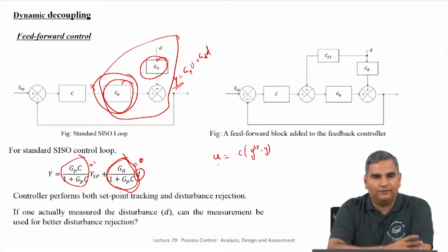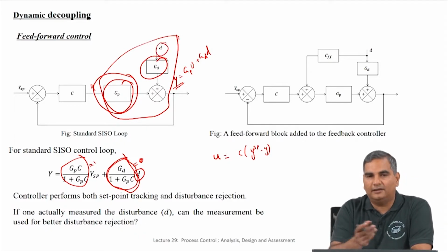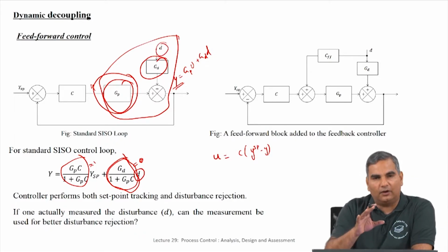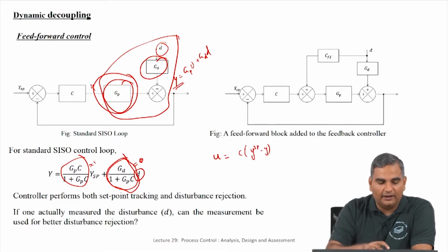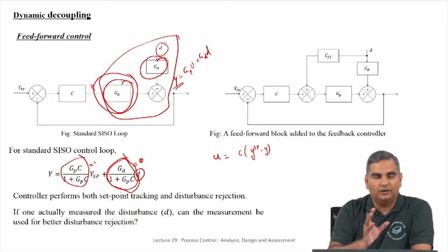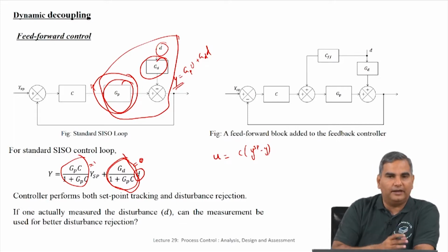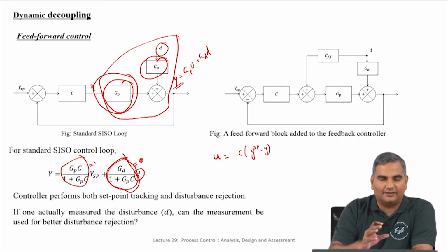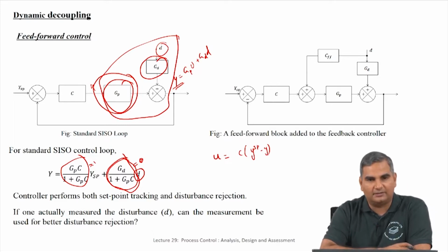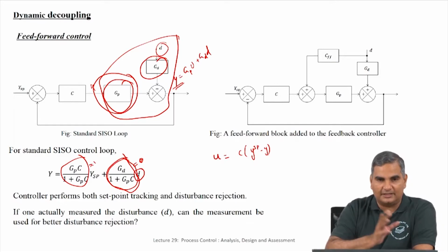The beauty of feedback controller is there might be many types of disturbances and they could take different values. We simply ignore all of this and then we simply look at driving the difference between what we want and what the actual value of the output is to 0. Okay. So, by just driving that and using a PI controller, we have shown that you can actually reject the disturbance without ever measuring what the disturbance is or knowing how many types of disturbances are there and what are the transfer functions and so on. So, that is the beauty of feedback control in its original sense.